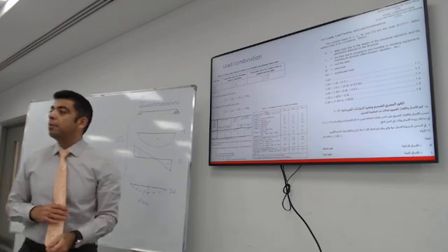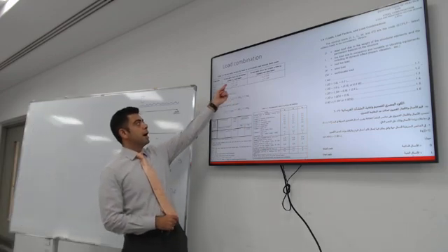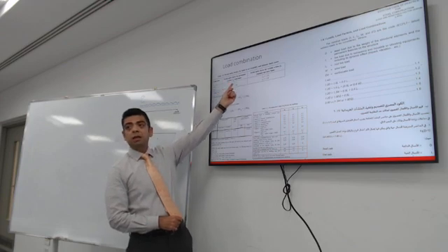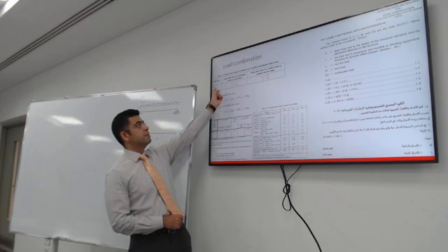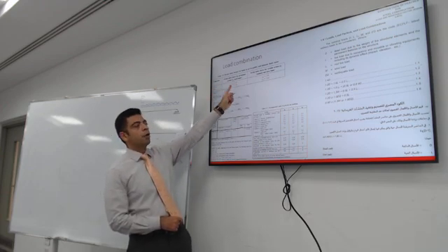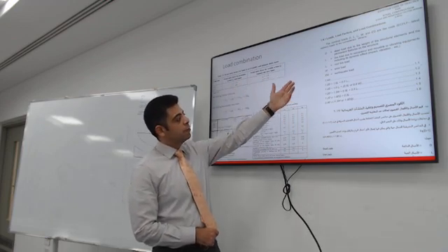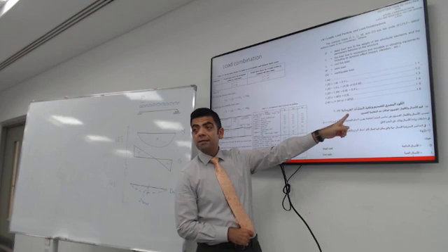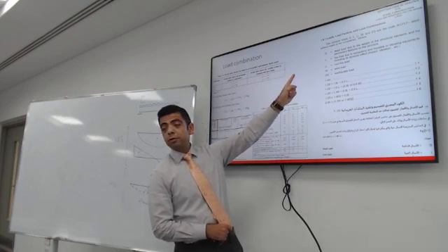These are the load combinations. The European code tells you for the dead loads, GK, you should use an ultimate limit state factor of 1.3 and a service limit state factor of 1. The Egyptian code has two different values, one for concrete design and one for steel construction.